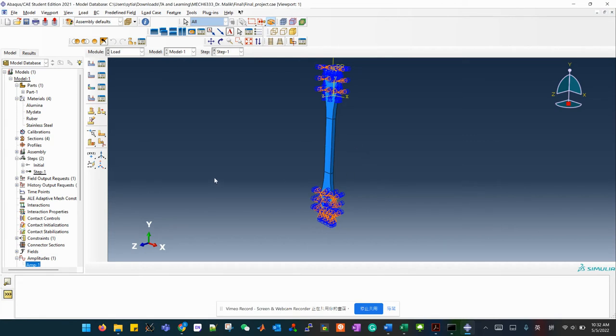The second thing is the materials model used for this analysis. In this example, I use standard dimensions for the actual tensile test as shown here. I'm considering both elastic as well as plastic deformation, but I'm not considering damage or such as the fracture of these tensile samples. And the materials are defined here.